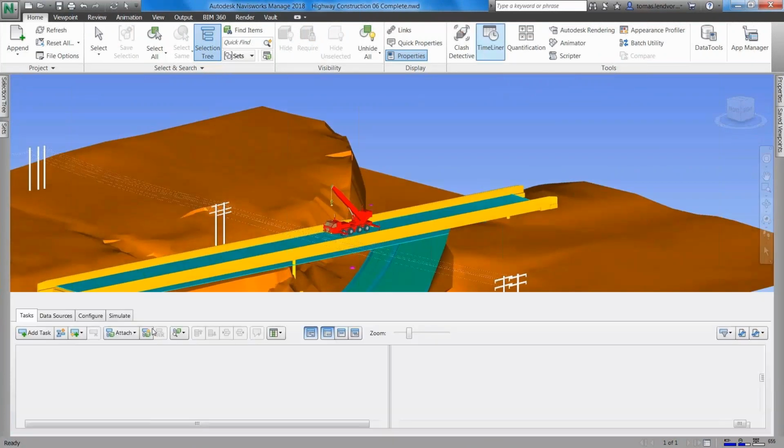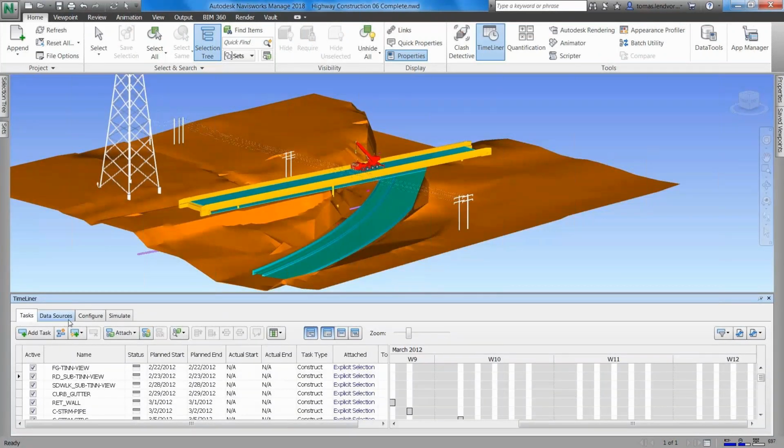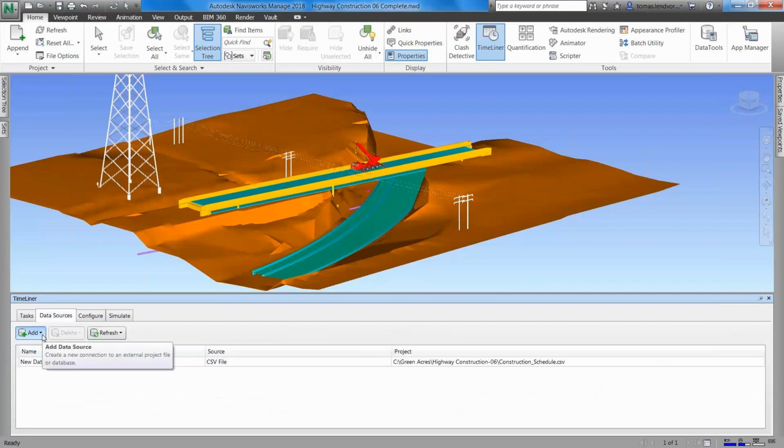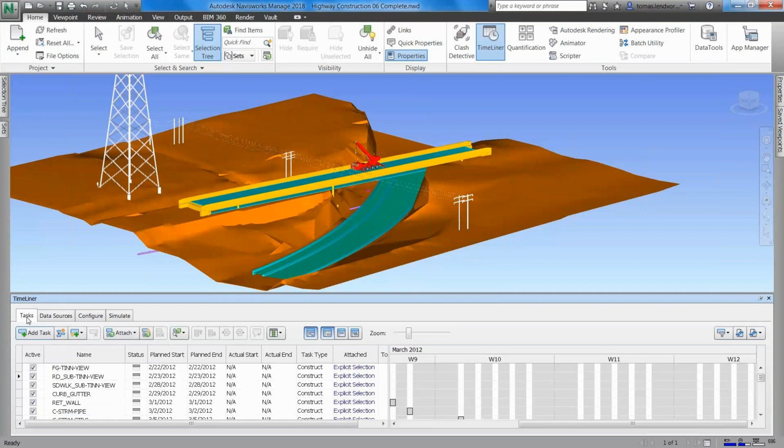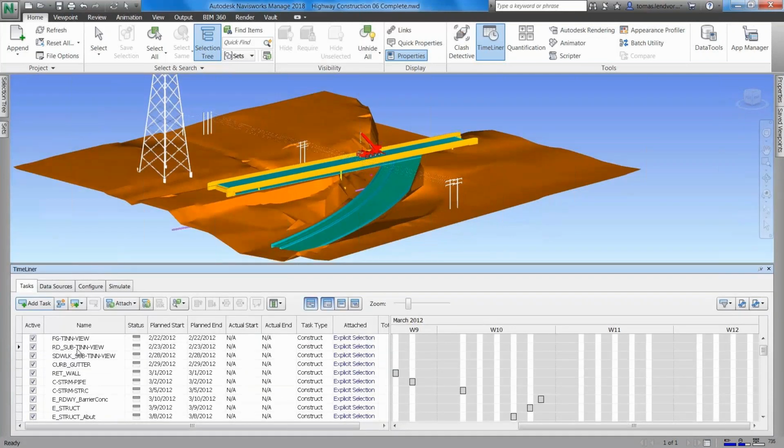And using the same solution, in another project I can very simply aggregate all data, the existing and the new, and what we can do is Timeliner. Basically, what we can do is construction sequencing, how the construction will be done. And this is something very useful on the construction side to see constructability, whether it really makes sense or not.